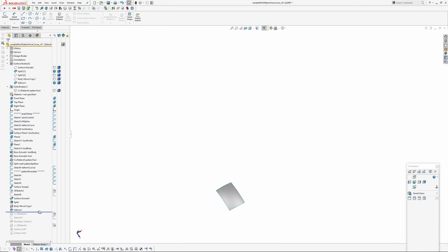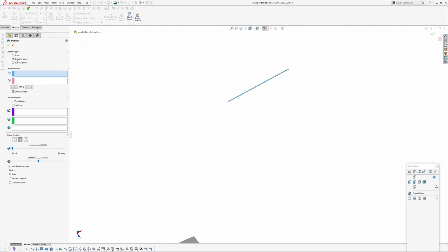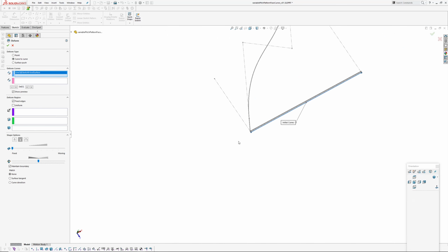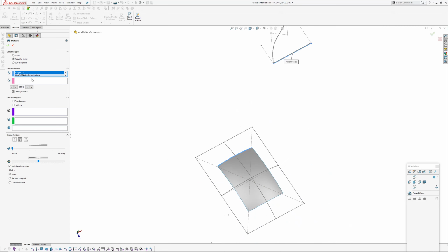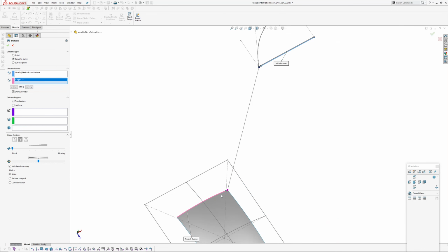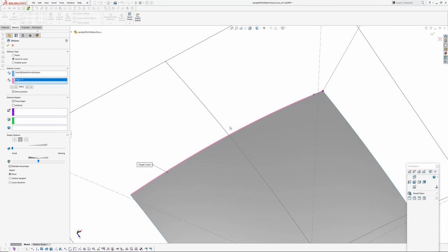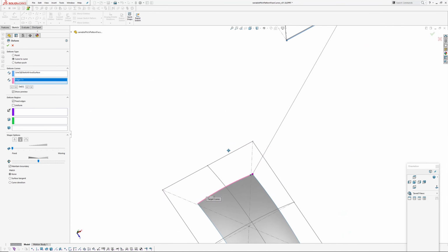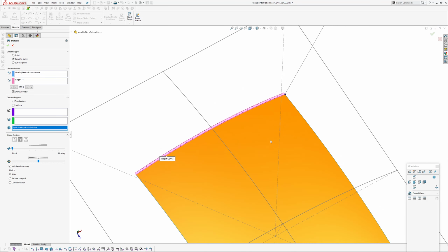Now if you haven't done this before, I'll just run through it quickly. Insert, features, deform, curve to curve, so you want to pick a base curve. In this case, it's that one there, and then the target curve, which is the end of the surface there. Oh, sorry. Got to swap into the target box before you pick it. Okay, and the ends aren't lining up in the same direction, so I want to come over here and click on here. So this corner will line up with this corner, and then you pick a body, which is our little ribbon there, which is chopped into segments.